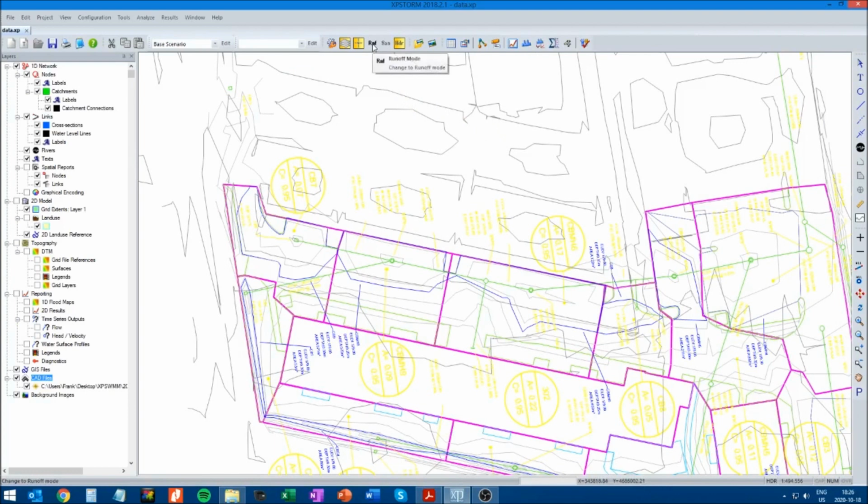First we want to make sure that we select the hydraulics mode, clicking on HDR at the top, and here we have nodes, so we'll click on the nodes and then basically just start clicking wherever there is a structure. At this point we're just going to create a node everywhere there's a structure, no matter if it's a CB or a CB manhole or manhole, and later we will change them such that the catch basins and the